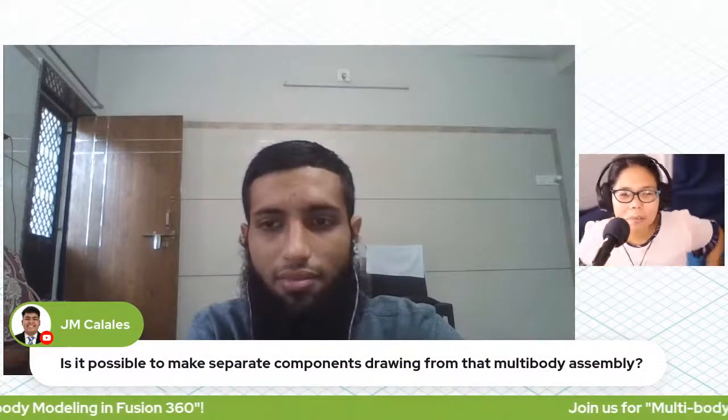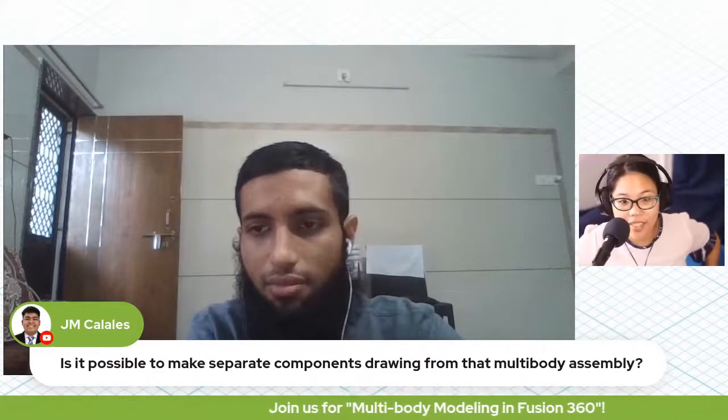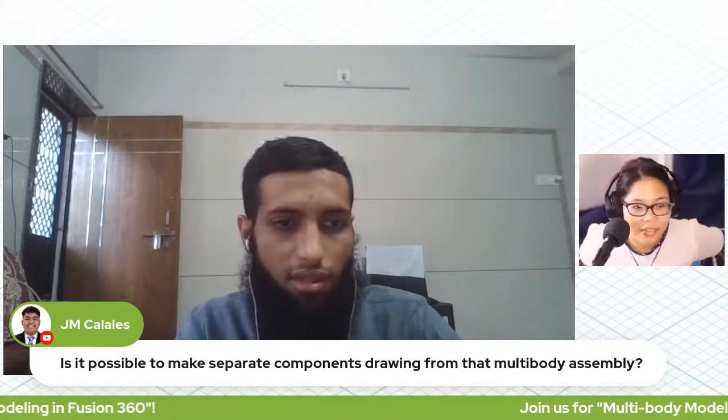Is it possible to make separate component drawings from that multi-body assembly? Yes, it is possible to separate the drawings from a multi-body assembly. For the drawings, you can directly use the drawing workspace within Fusion 360, or if you want to export the drawing files or sketch files, you can directly export them into CAD format. It's very easy.